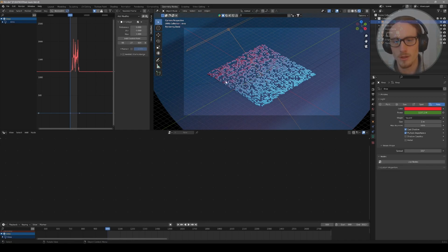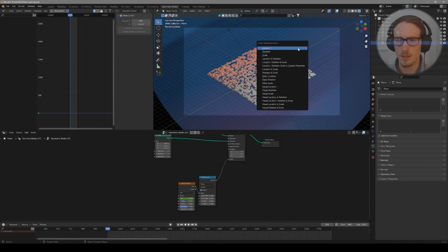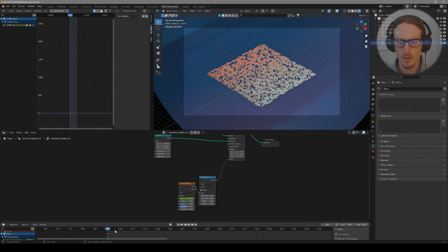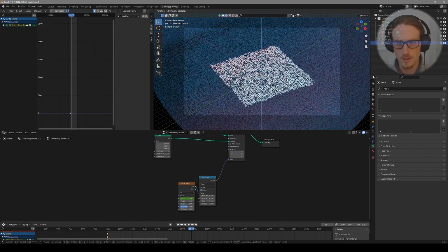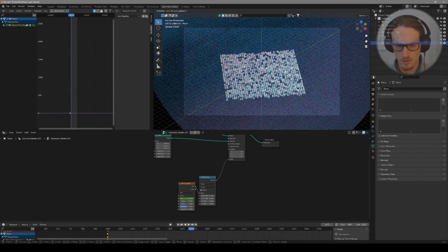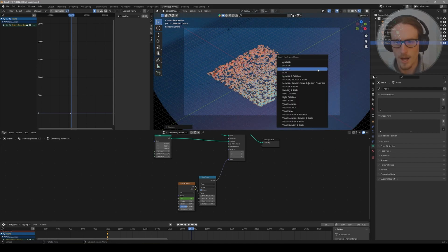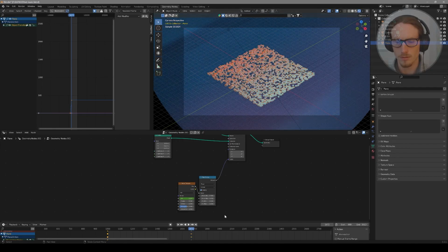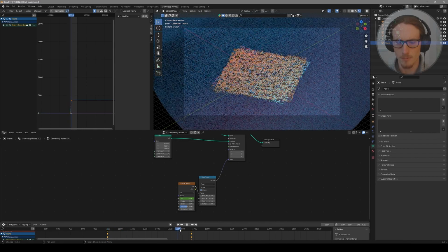One last step, you can make this look a little bit more dynamic by animating the entire object. Go back to your start, select your object, and press I to insert a keyframe for rotation, for example. I've now inserted a keyframe there. I'll scrub forward in my timeline, press R, Z to rotate on the Z axis, and then type 360. Then I to insert that keyframe for rotation. So now we've told it to rotate 360 degrees in that amount of time.